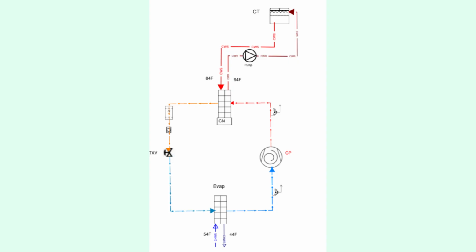Condenser system, rejecting the heat. After absorbing building heat, the refrigerant must reject it. This happens in the condenser, and the method depends on the type of chiller. Air-cooled chillers reject heat directly to outdoor air using fans. They are packaged, simple, and ideal for buildings without cooling towers. They work well in cold climates, offering year-round operation without freeze issues.